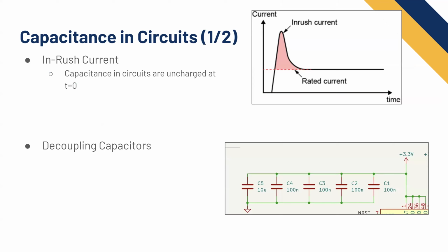And so it's going to just be the voltage over whatever resistance is naturally in your conductors. You're going to overshoot on the inrush, and then you'll get down to whatever current your board is actually pulling to operate the components, because the capacitor is already charged. If this is extremely bad, oftentimes you'll need an inrush current limiter, which is basically what pre-charge is, in a sense, an inrush current limiter.